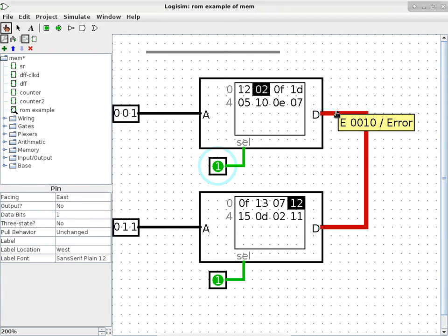What is stopping the current from becoming, quote-unquote, infinite? There are a few things, but I'll let you guys name a few. Is it power, positive voltage, negative voltage? So when you connect something like this, what is limiting the current? Resistance, exactly. So there's resistance associated with the transistors. When you look at the transistor, it's not a perfect switch, okay? It is not a lossless switch. There's always a little bit of resistance here, a little resistance here, and also here. The resistance is what is limiting the current to a certain amount. Is that okay? Okay.